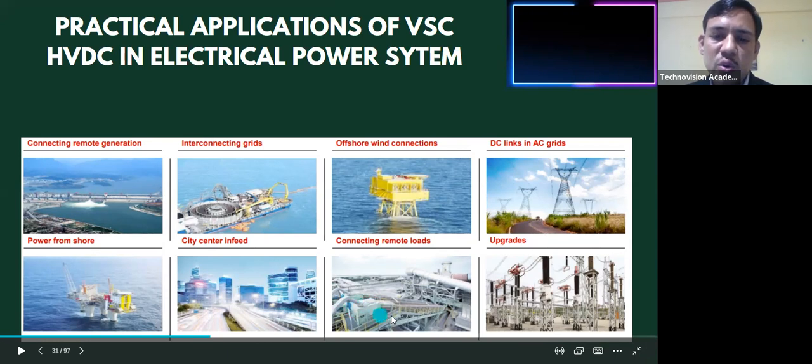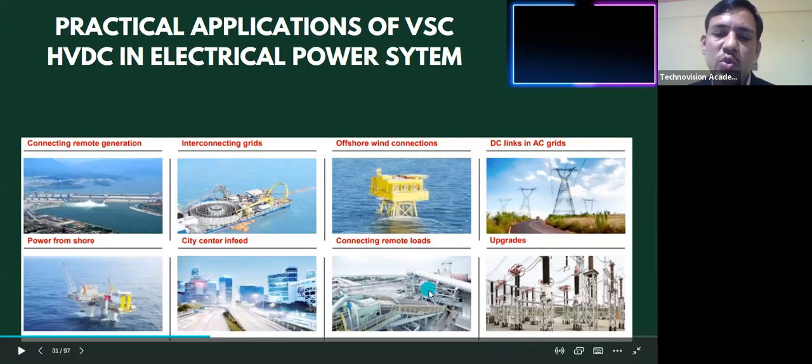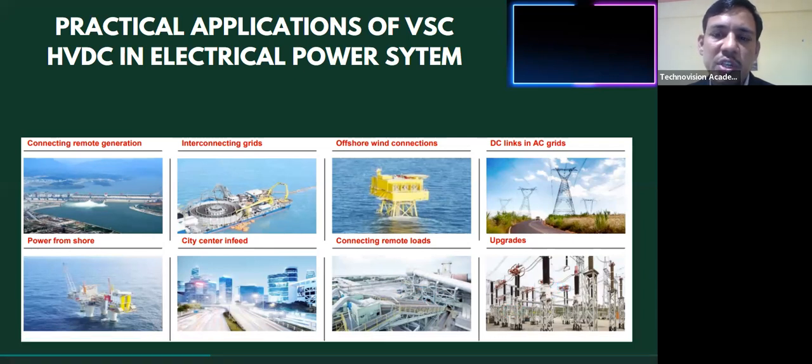So we'll discuss on that also. Then connecting remote loads, any remote loads, even this VSC HVDC you can use for the distribution side also. Suppose you have some DC load requirement, especially where there is less generation or no generation available in that area, so you can supply this power to that load also, and you can upgrade the conventional HVDC or your EHV systems with the VSC HVDC system.